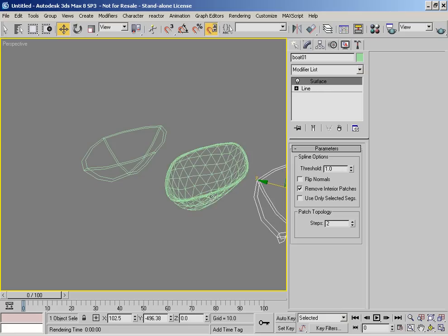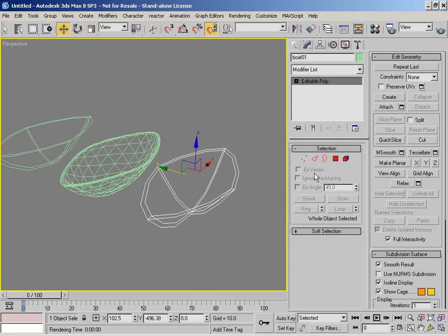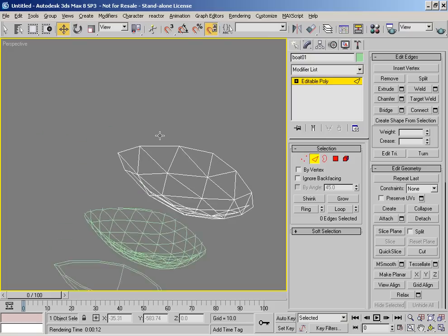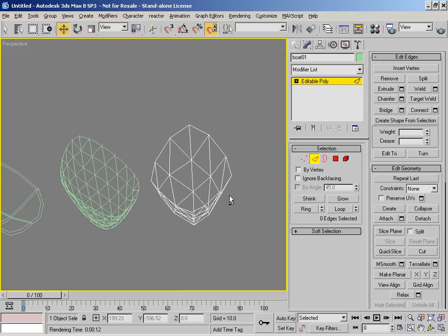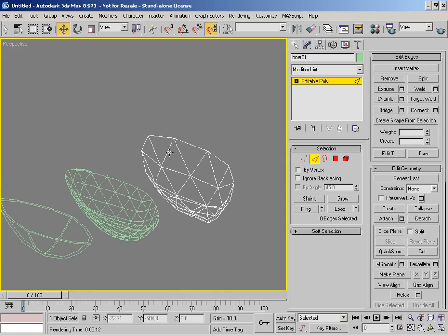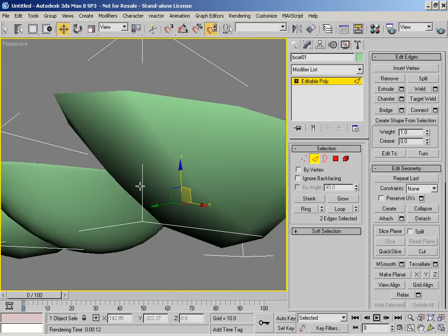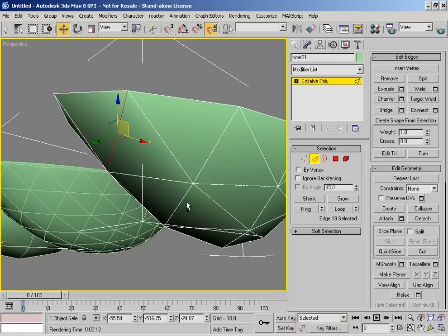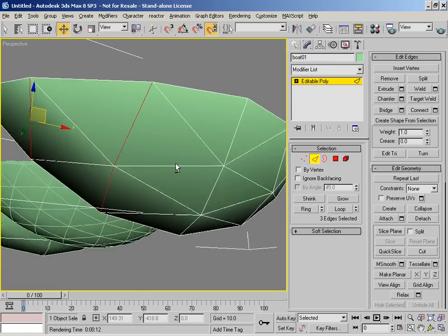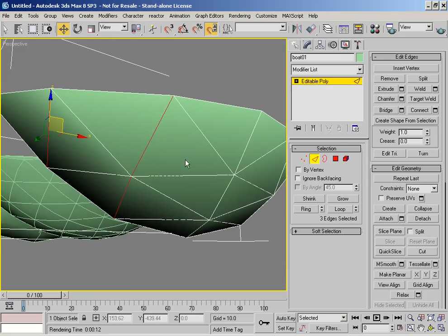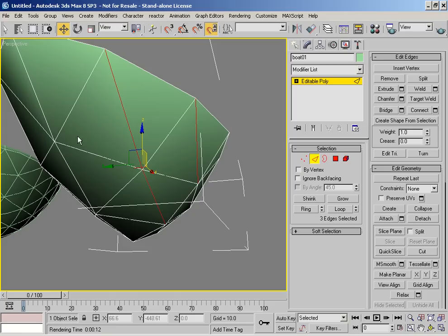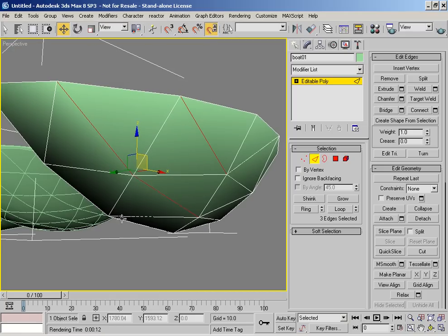copy the result, collapse it to an editable poly, and then we can clean this up relatively easily, because we can simply go, okay, you're basically 2 tries, we can get rid of you, we can get rid of you as well, or even maybe that one, and maybe just have 2 sets of tries at the top, at the front here. So the amount of tries that we can reduce is obviously getting more favourable.